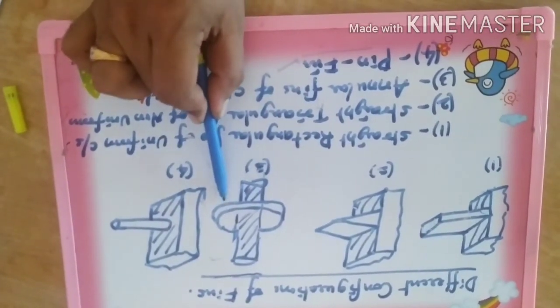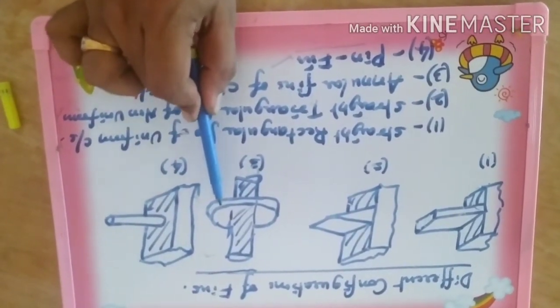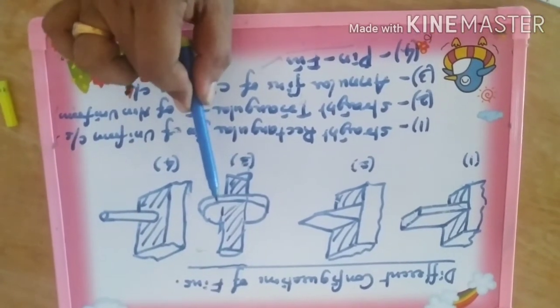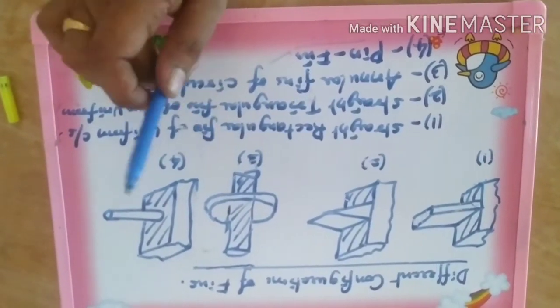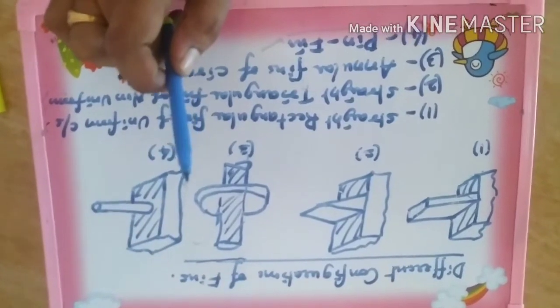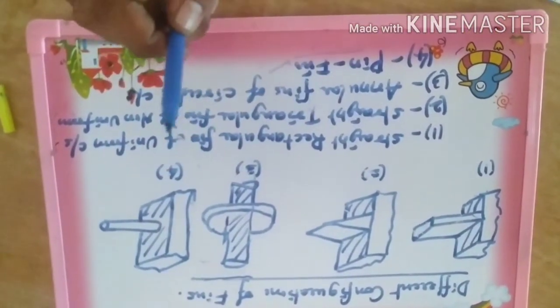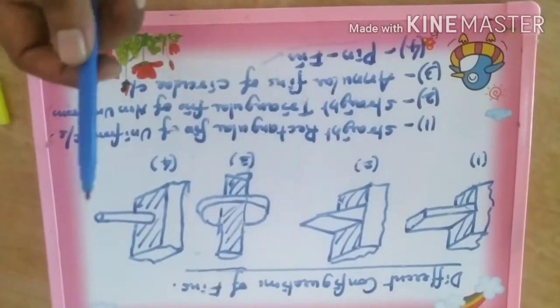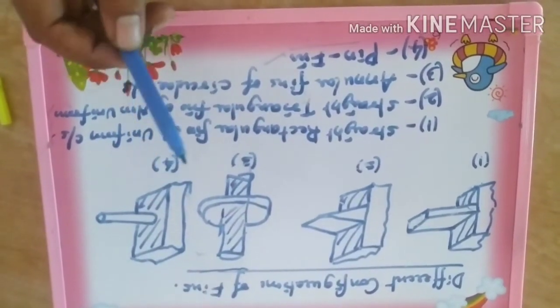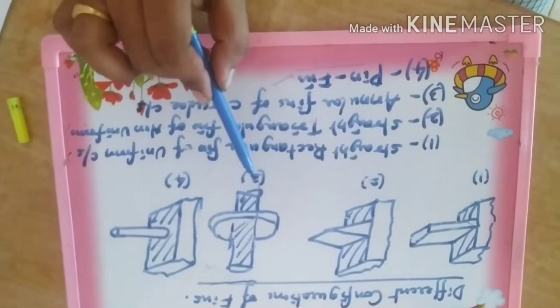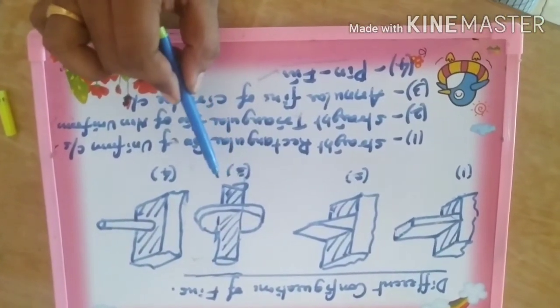Altogether they are called annular fins. Annular here refers to what? It refers to the circumference of a given base surface. So if you attach fins, maybe of different cross sections, to the base surface along its circumference, then those fins are called annular fins.